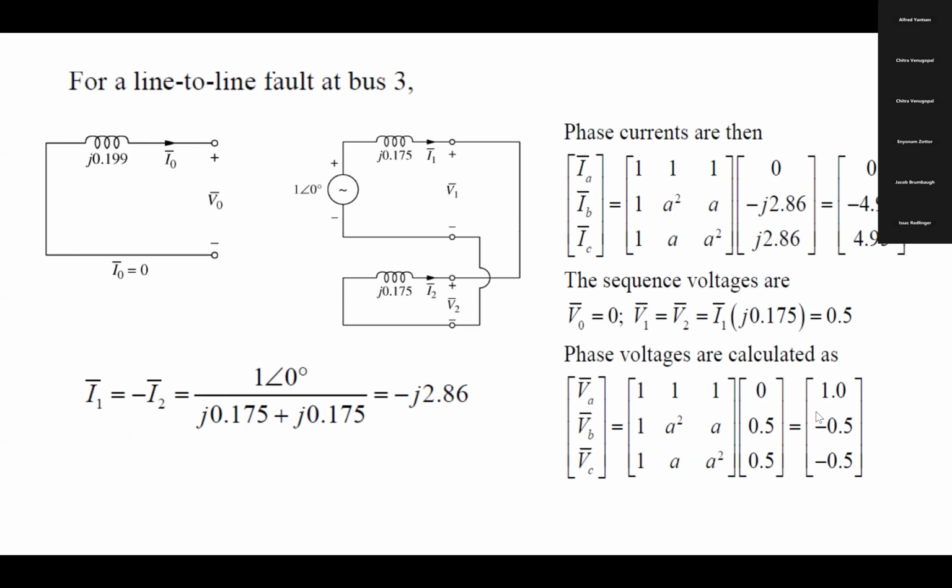Now trace the current. Why am I saying always trace the current? Because connecting them in parallel doesn't mean the current should be different. It may be the same. So you connect the circuits in parallel, but trace the current to identify whether the positive sequence current and the negative sequence current are getting divided or they are the same. If you know this, then only can you identify whether the resistances are coming in series or in parallel. Even though the two circuits are connected in parallel, it doesn't mean the two resistances must be in parallel. Okay, that is what I am trying to emphasize here.